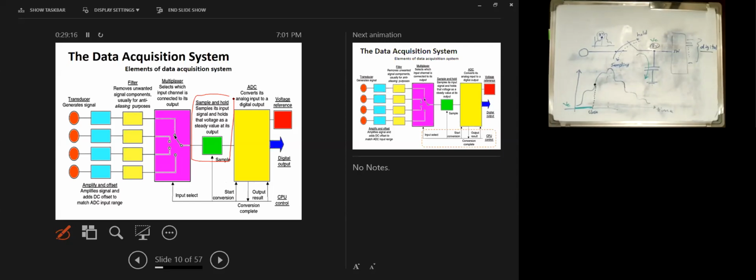In other words, its voltage will not be 3 volt in 0 time. So the capacitor will start to charge like this, right? The capacitor will start to charge like this. So now the question, when to open the switch? If I open the switch in 0 time, then the capacitor voltage will be 0 volt, right?